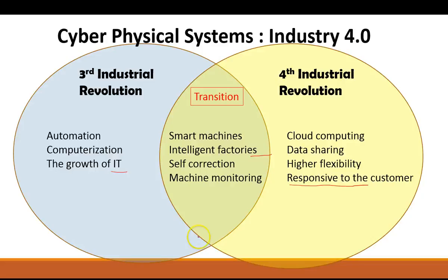The ability to self-correct. One of the technologies that were developed by NIST and through the U.S. Army, the Department of Defense, the smart machine platform initiative, was the ability for machines to be able to both self-monitor and correct based on different types of feedback and different types of sensors. So the idea of the ideal smart machine would be the machine being able to change due to work conditions, different types of forces, different types of pressures at the tool or anything that you're able to sense on that machine and respond to it through a series of algorithms.